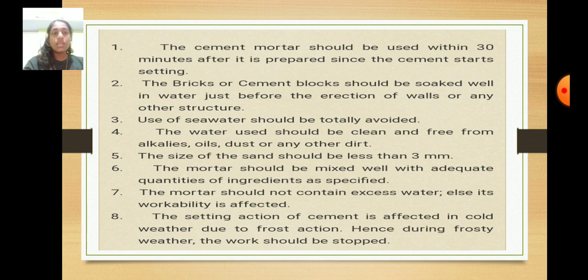These are the precautions. The cement mortar should be used within 30 minutes after it is prepared since the cement starts setting. The brick or cement block should be soaked well in water just before the erection of walls. In any other structure, use of seawater should be totally avoided. The water should be clean and free from alkalis, oils, dust and any other dirt. The size of sand should be less than 3 mm. The mortar should be mixed well with adequate quantities of ingredients as specified. The mortar should not contain excess water, else its workability is affected. The setting action of cement is affected in cold weather due to frost action. Hence, during frosty weather, the work should be stopped.